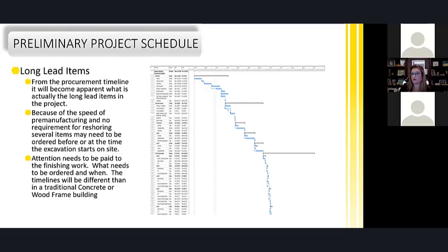One of the largest mistakes we made in Brock Commons is we truly didn't understand how fast we were going to build, and it was pretty amazing to see the superstructure and the envelope panels go up within 3 days in a 3-day cycle. However, our interior finishes were nowhere near that timeline because we simply didn't understand at the time how fast the building would go. We had tried to bumble along and do some pre-manufacturing, do some mechanical pre-manufacturing and pre-purchasing and having that install. But in fact, when we got down to it, there was at least 5 to 6 floors empty at any given time on that building because we simply hadn't set up the rest of our trades for that level of intensity and set them up for that level of success.